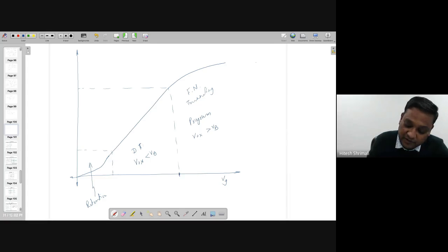If you are working at 180 nanometer, its typical voltage is 1.8, or let's talk about 130 nanometer, where you are using VDD of 1.2 volt. But when you have a floating gate device at the gate, you are going to give more voltage than 1.2 volt, which is going to achieve such a condition, and you can program it, right?